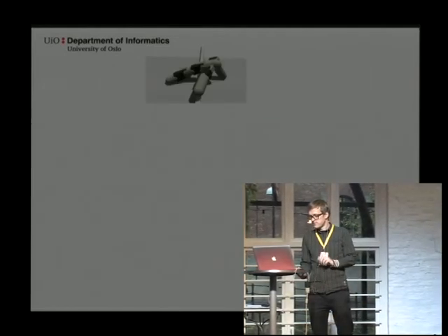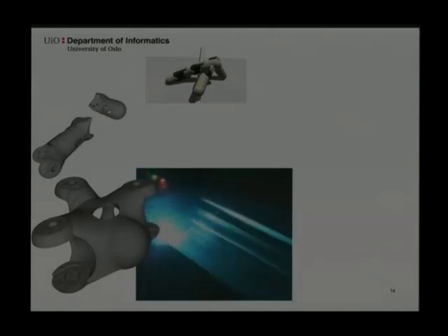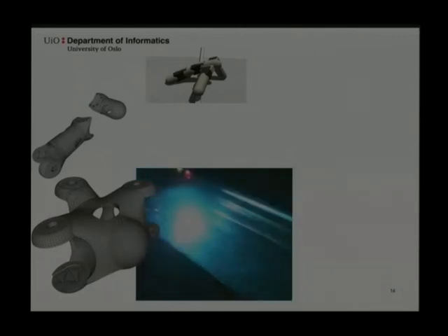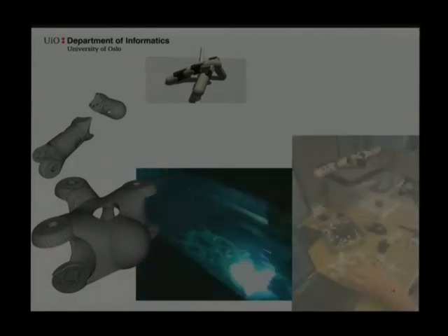Once you've selected your robot, we push a button in our system. Of course, we coded the algorithms to do this as well, but we generate a triangular mesh from it. It's a mix between models from SolidWorks that we modeled and shapes generated from these basic building blocks. And then we 3D printed it. This is done on this Connex 500 printer, which we are blessed or cursed with having. It's a slightly different robot being printed just now, but that's the time lapse I had available.